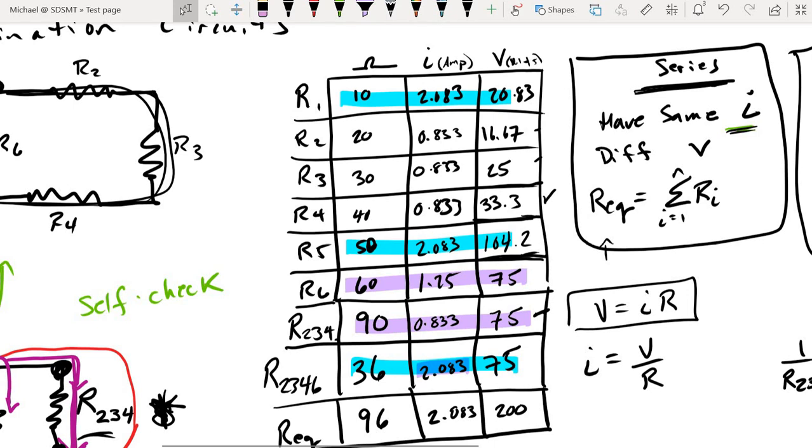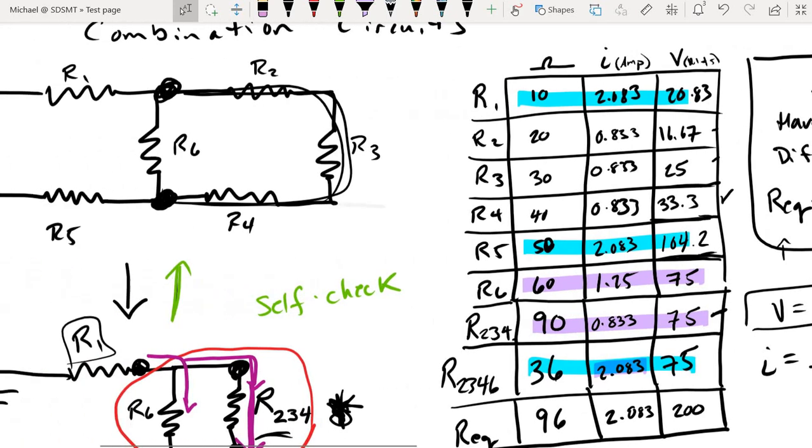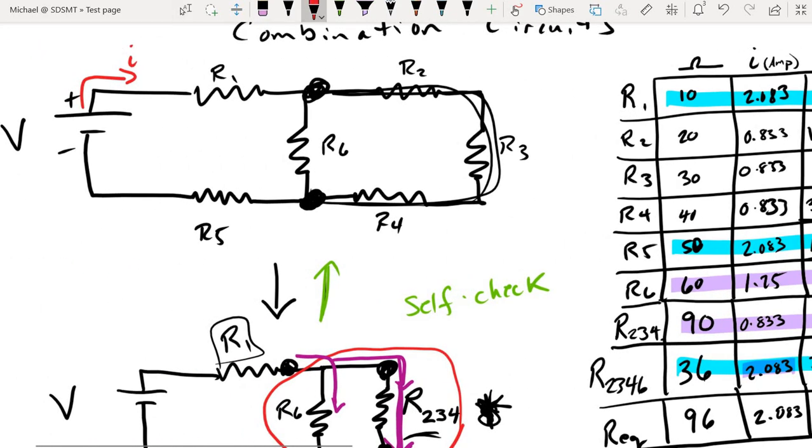But what I will ask is, or let me start over. What is the total rate of energy dissipation for the circuit? So remember, every one of these resistors is producing some heat, and the rate of energy dissipation, that's just fancy terminology for power.